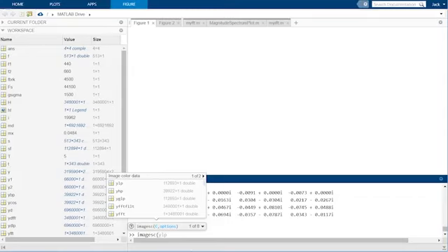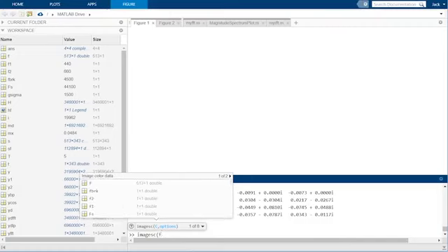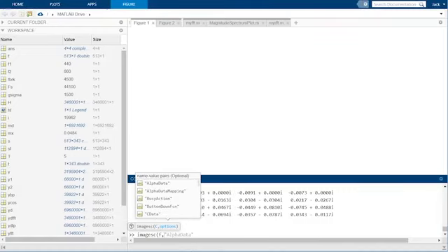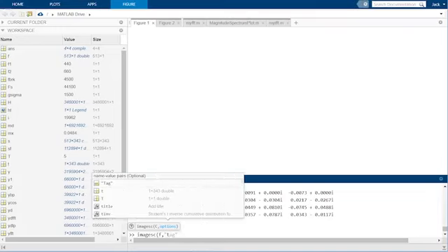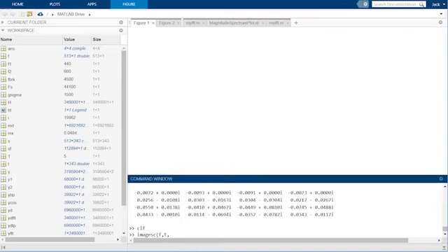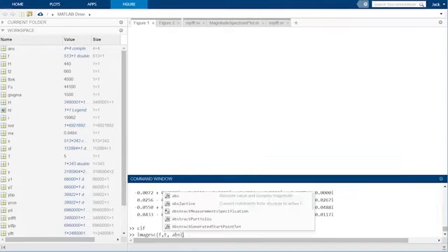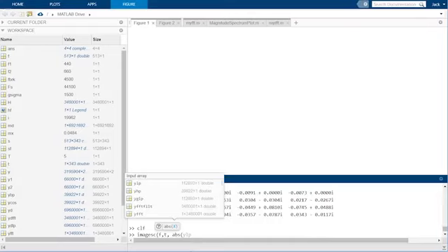We'll see more about image display in the following lesson on image analysis with MATLAB. We provide imagesc with the x-axis coordinates of each column of the matrix to be displayed as an image using the frequency vector f. The y-axis coordinates of each row of the matrix to be displayed using the time vector t. And then similarly to the magnitude spectrum plots that we've done, we want to display the magnitude of the FFT components.